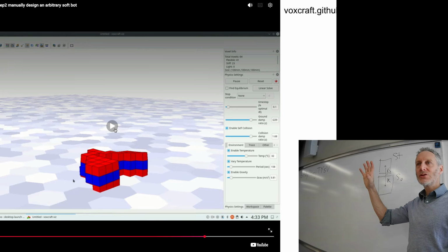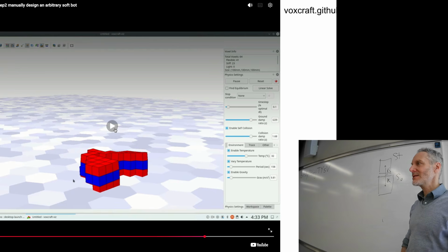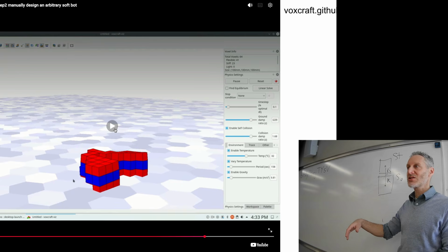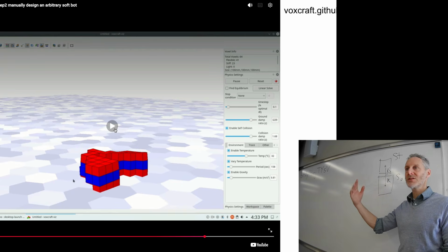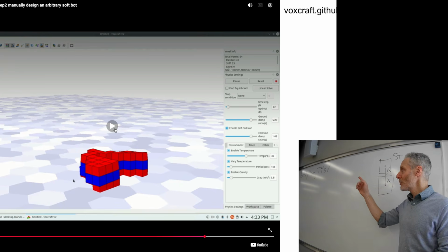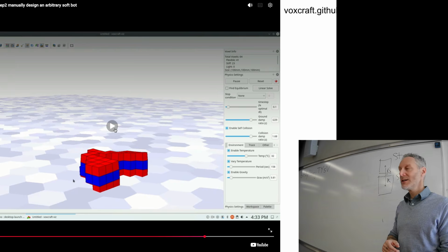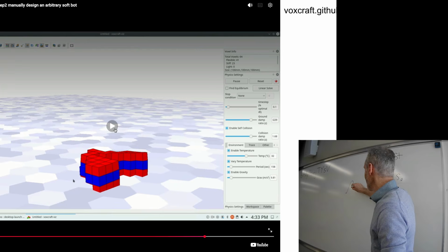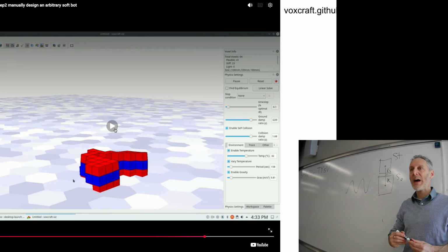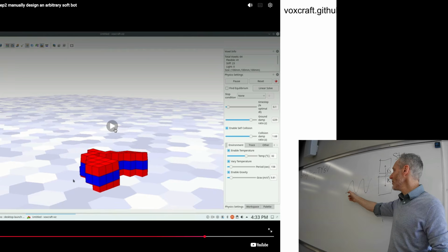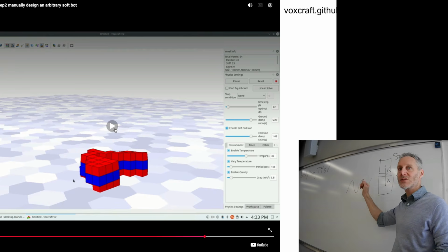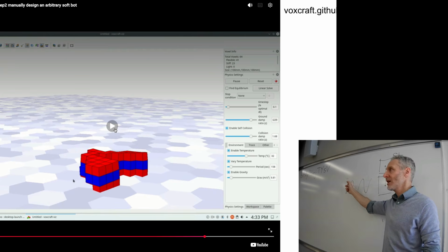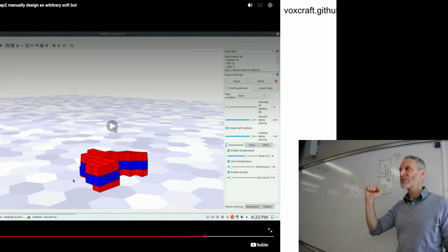So what we just talked through actually are, again, the objects and joints. There's no strict joints here. It's the beams connecting these pieces together, but we've got a physical structure, and now, surprise, surprise, we're going to start to layer on motors, sensors, neurons, and synapses like we did in the Carl Sims experiment last time. So the first thing we're adding on here are motors. So we've got some motors that are controlling this robot, and we're connecting a central pattern generator, something that just spits out a sinusoidal pattern, and it's sending these values, high desired force, low desired force, to the motors.